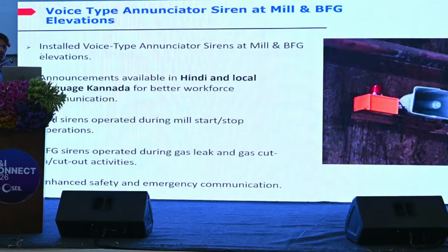And this is the first implementation we have done in our mill system and BFG system. This is the annunciator siren in mill and BFG. We have installed it for safety purposes. Whenever the mill starts or stops, it will give a siren in Hindi and the local language Kannada, so that the manpower working over there will know the mill is going to stop or start, so that they can move to a safe place away from the equipment.